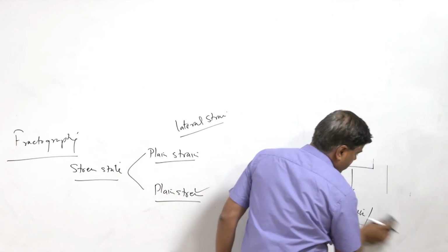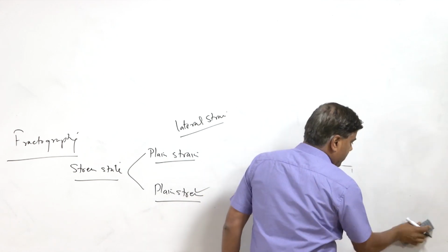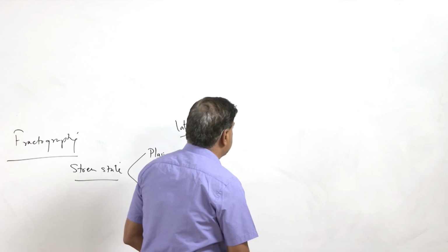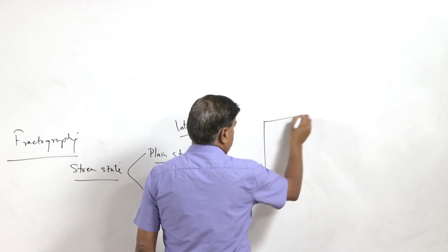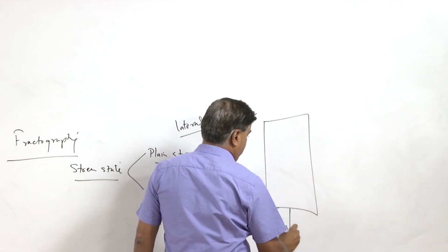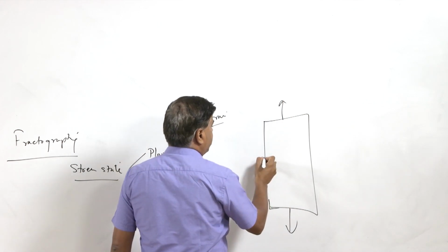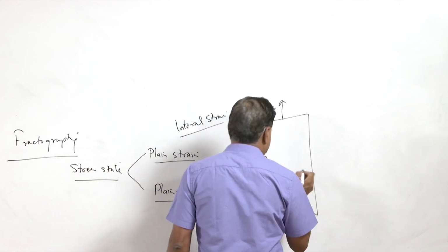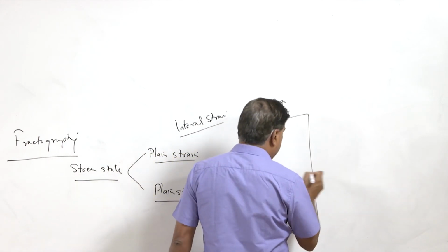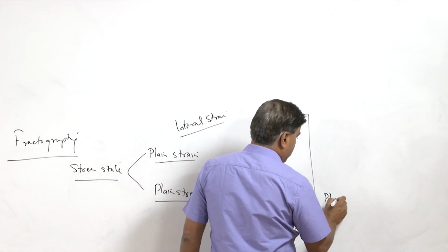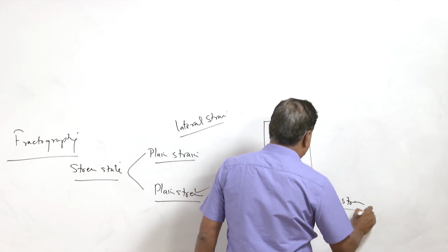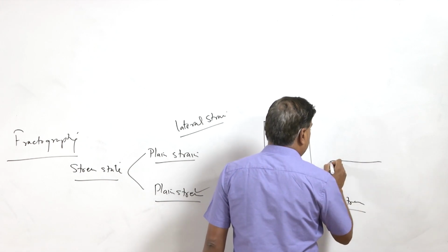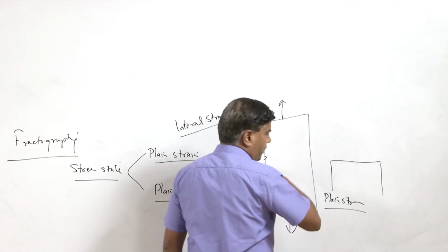This is the case when the fracture starts with the growth of a crack from the center, where plane strain conditions exist, but there can be other situations where the fracture initiates from the surface. If the fracture initiates from the surface, even under static load conditions, then even under plane stress conditions we do not find any shear lip, and the fracture surface is again flat.